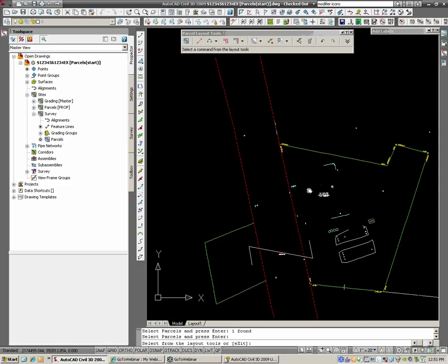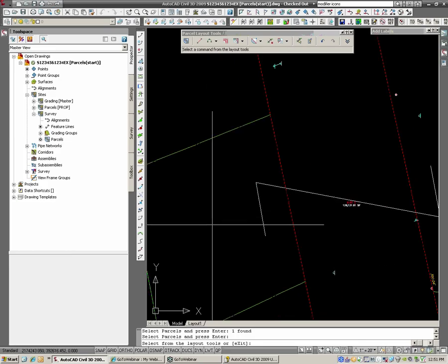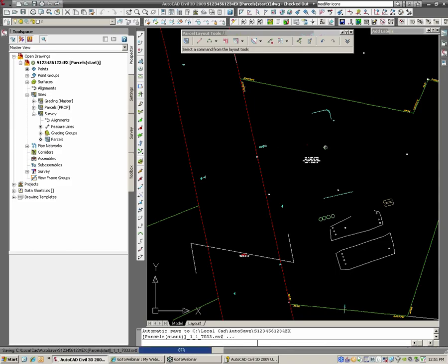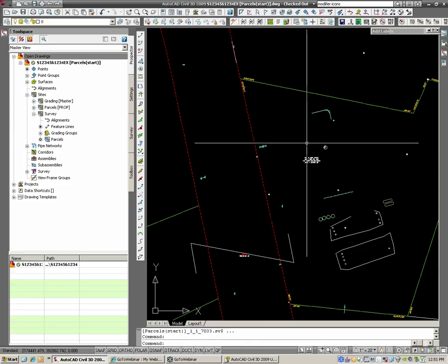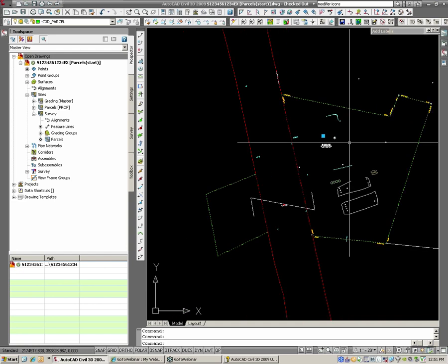Now this area is the combination of these two parcels. You can see the marker on this side even went away. So when I click this red parcel marker, hit X to exit the command, and this toolbar will go away. When I click this parcel marker here, both sides highlight. So parcel union is the big takeaway from that.